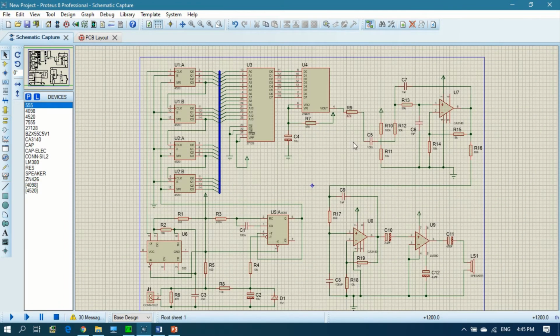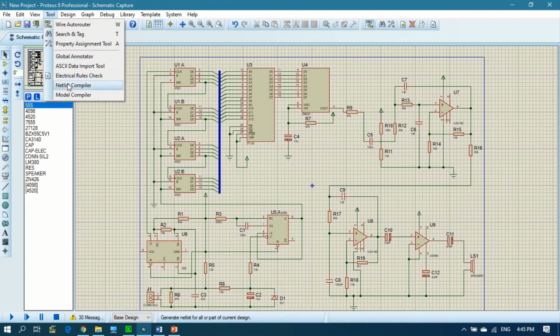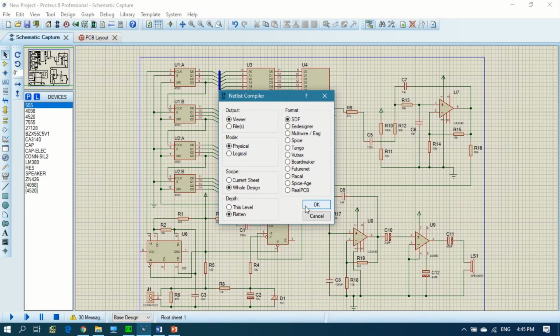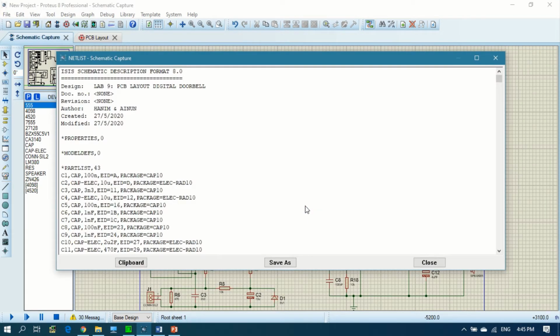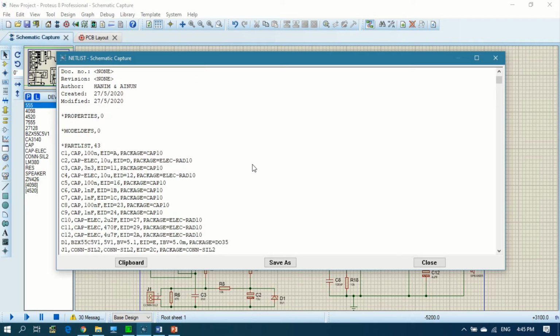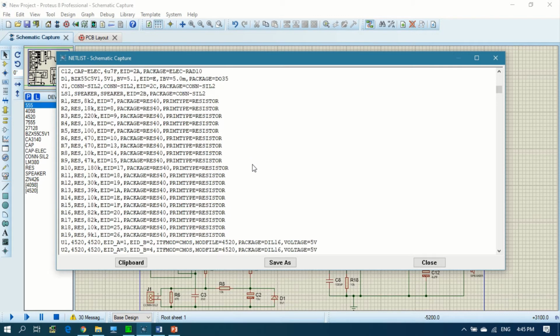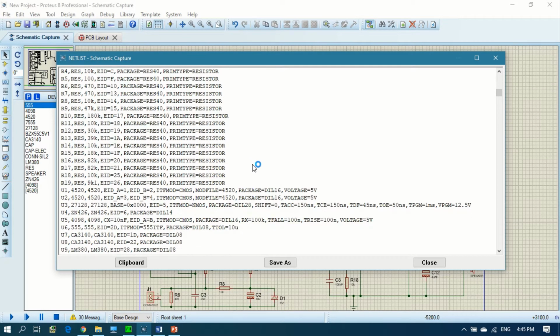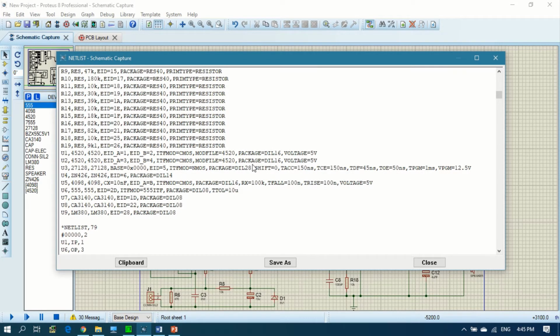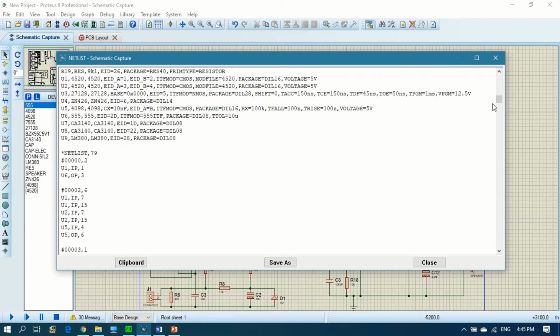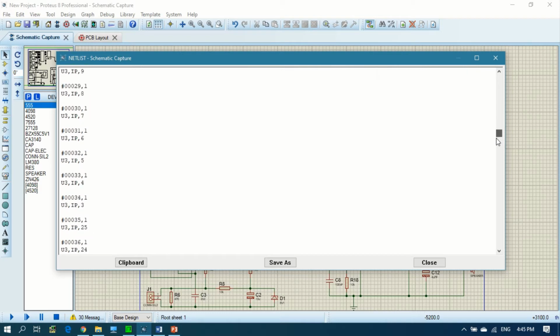Okay, next is netlist report. For netlist report, this is to prevent unexpected errors from occurring, as it serves an extra verification for the design and also ensure that when the manufacturer is completing the electrical test of the circuit board, the process will be accurately testing against the intended design.